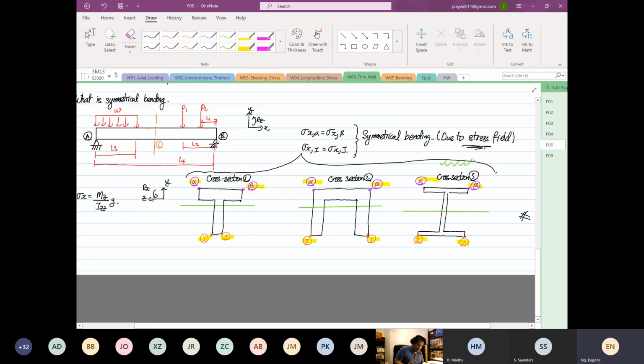So the stress symmetry, okay, symmetry over here means stresses about the vertical axis, where the stresses on the left hand side is equal to the right hand side. Nothing to do with the centroid. Okay, the centroid is just making you comment. So where I drew the pink line, that is the axis of symmetry for your stresses.